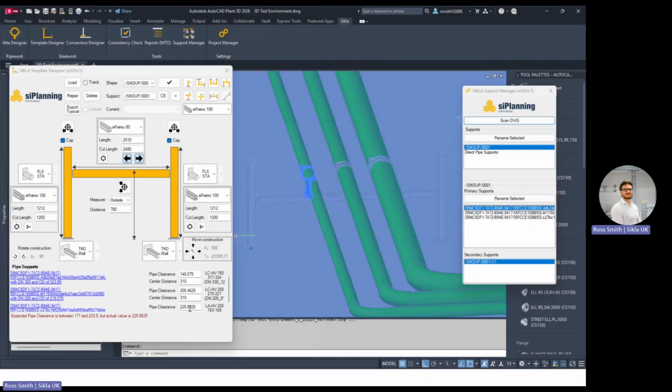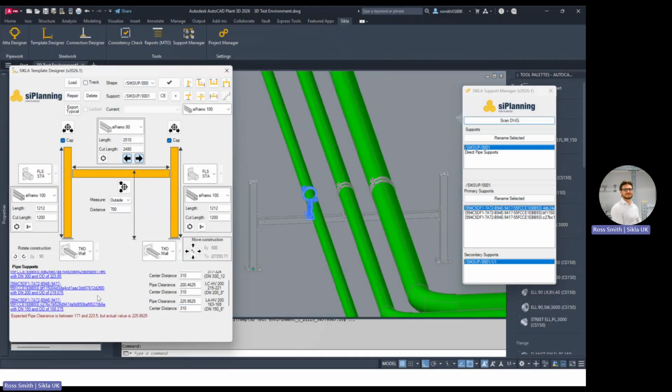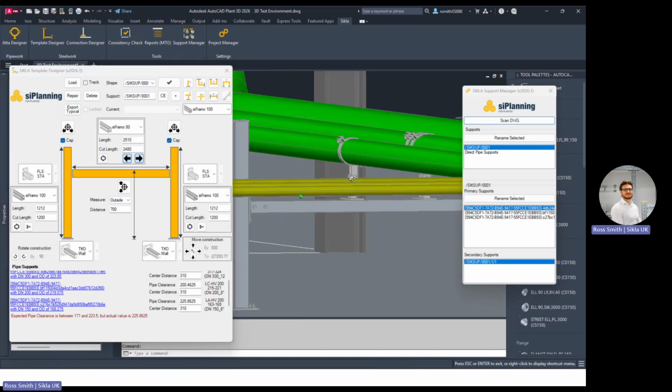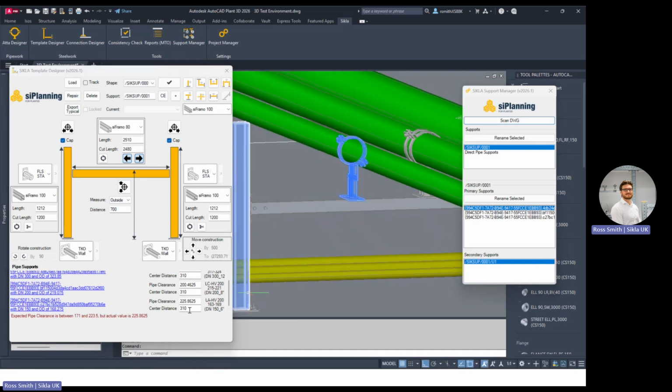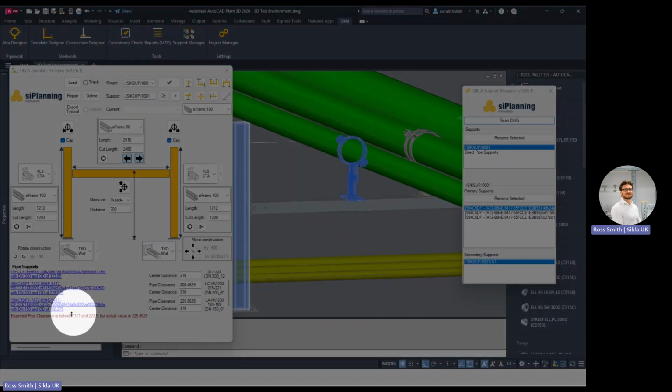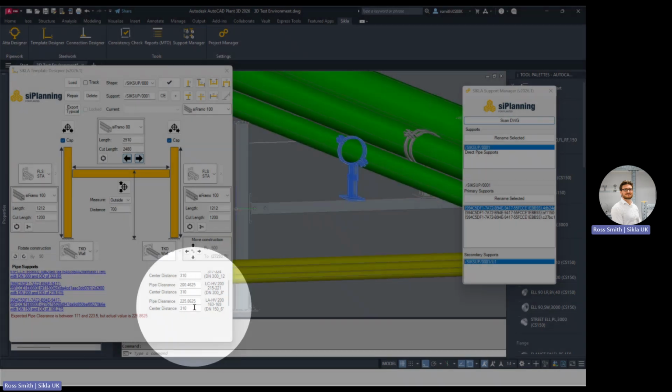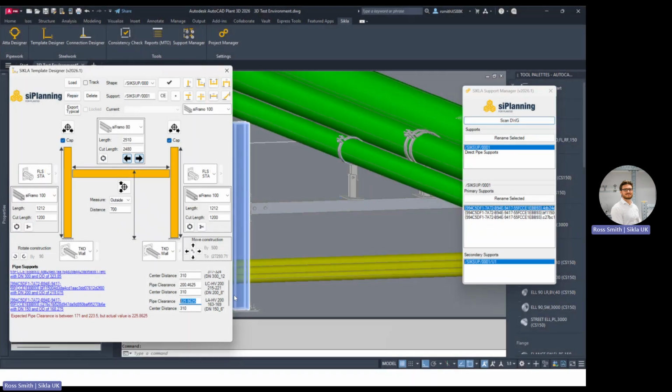And I can see it's this pipe shoe here, because it extended outside of its range. Okay, so let's drop this to within what it suggests. It's telling you the lowest it can be is 170 mil clearance. This is underside of top of steel to underside of pipe height. So let's change that to